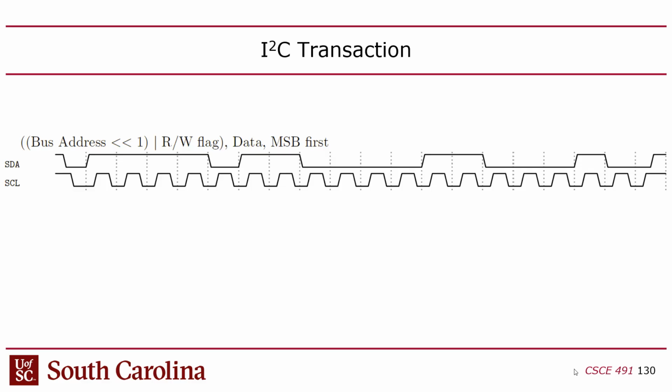And then this is our read-write bit, which is a 0, which means write. And then the 9th bit better be 0, because that's our acknowledgement. So you hope the 9th bit and the 18th bit are 0, or every 9th bit should be 0, which it is.